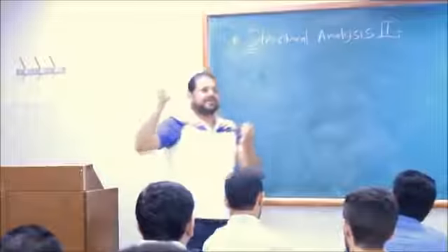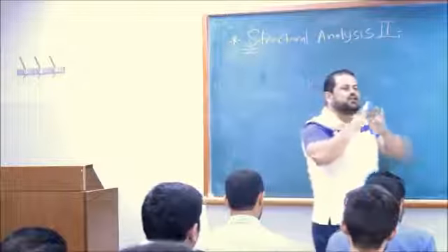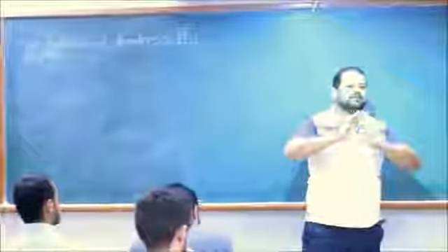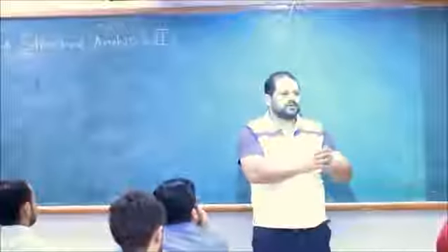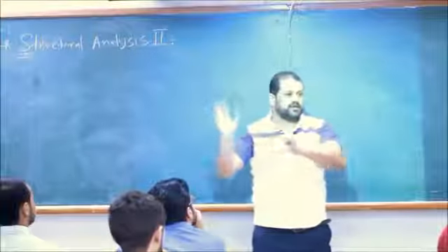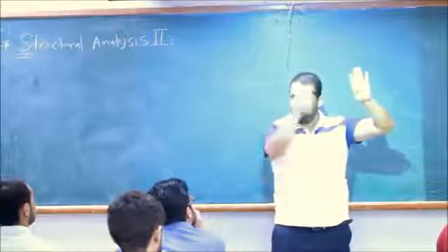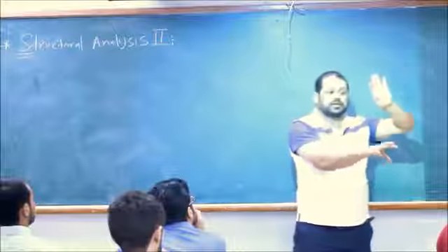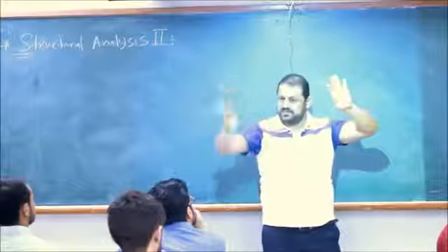That's it. Stress is what? Guys, this is Hooke's law, the first fundamental concept in mechanics. Hooke's law says sigma equals E epsilon. Epsilon is the same. Stress in the steel will be E steel times that strain. Stress in the concrete equals E concrete times that strain.